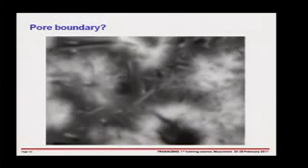And finally, we come to the pores. As I said previously, the problem is that we don't see a sharp boundary between pores and not pores. This shows a polished section at very high magnification. In this kind of image, we're also having a problem with the resolution of the backscattered method. But you can see here, this is a needle of ettringite, which would be a few hundredths of a micron in diameter. It's looking rather fuzzy, but this is why we cannot well pick out the pores.